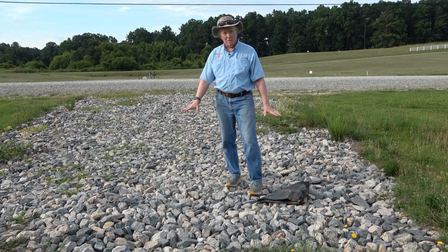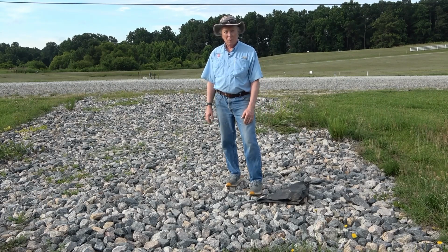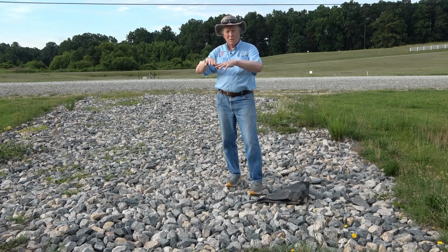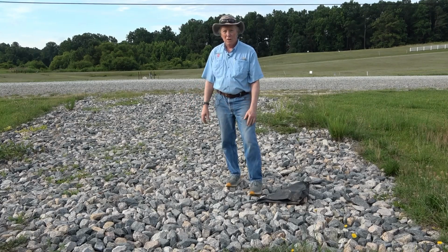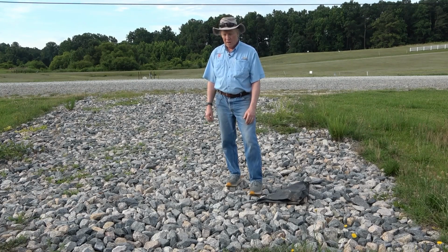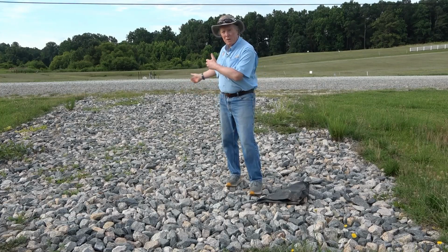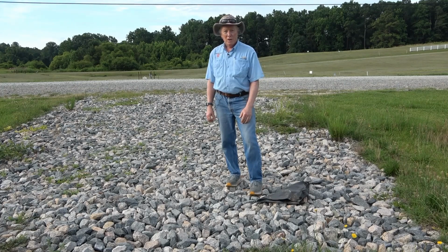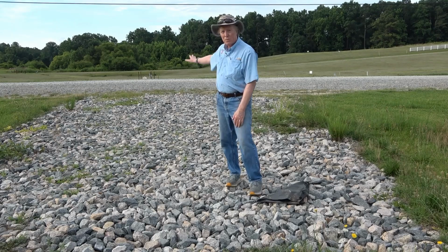Now, there are some alternatives to this type of entrance. There are some commercial products, such as those that are made of corrugated metal. They also vibrate the tires as the vehicles are moving out onto the road. There are some that are based on cross ties. Those are used in forestry frequently. And then kind of scaling it up a little bit, we can actually park somebody with a pressure washer out here and they can wash those tires individually. Those are cases where we really want to make sure there's not any tracking out onto the road.